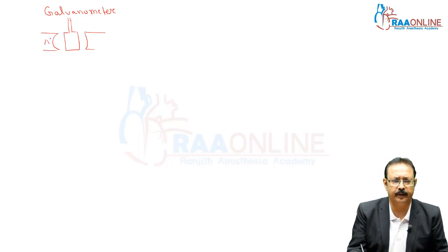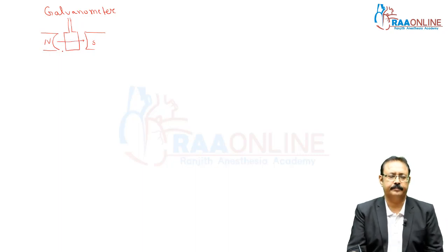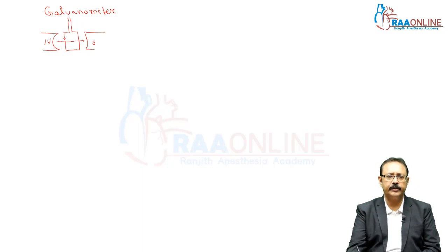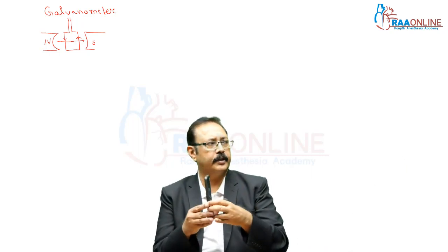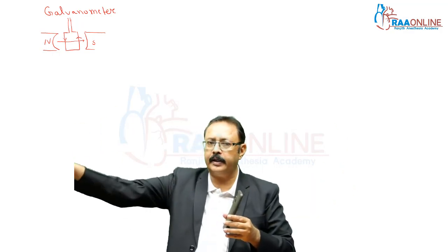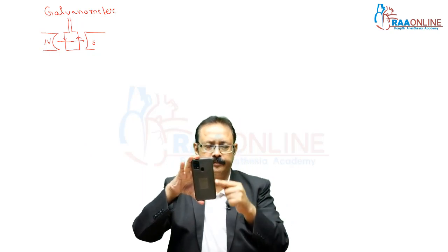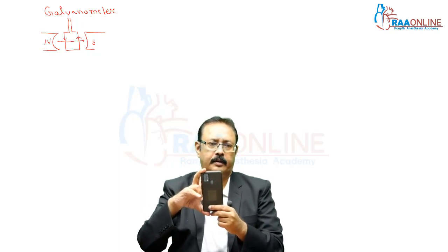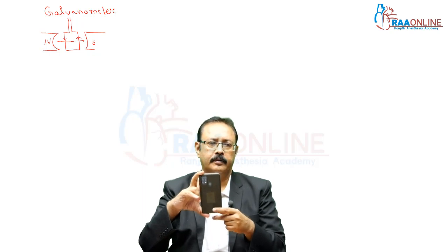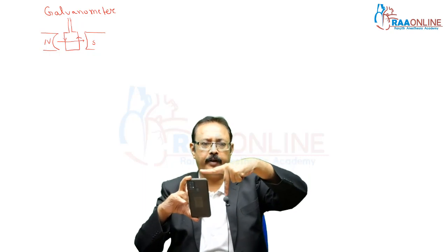Suppose it is the north pole, it is the south pole. It is the direction of your magnetic field. Current is flowing through this wire, this. So what will happen? This is your coil. This wall is the north pole, this wall is the south pole. Current is coming downward in this. In which direction will this arm feel a force? Fleming's left hand rule. Forefinger should be in the direction of the field. Central finger in the direction of current, outward.